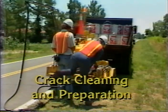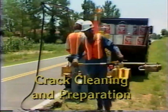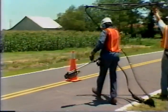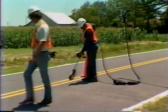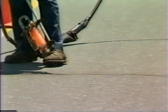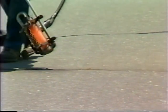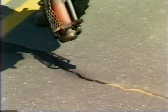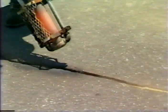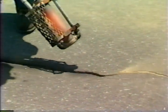The second step is crack cleaning and preparation. A clean and dry crack is essential if an effective bond is to be formed between the crack sealant and the pavement. Clean the cracks with compressed air, or preferably a hot air lance. Compressed air effectively removes dust, sand, and other incompressible matter from the crack, providing a clean face for bonding. The hot compressed air lance combines high pressure with a flame to heat the air. This dries and cleans the crack at the same time.